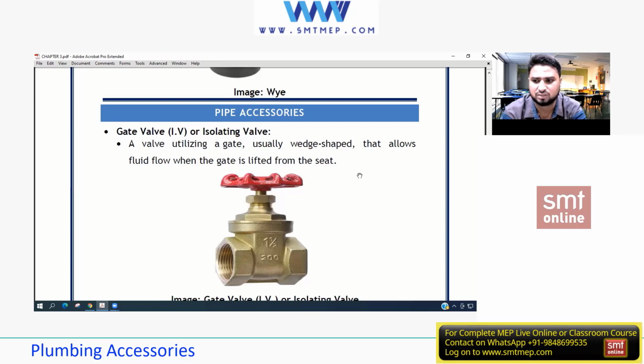Why? Because it's not recommended, for example, in a high-rise building with 10 bathrooms and 10 kitchen areas, that I totally disconnect the complete water supply just for one person who's suffering, right? So that would be open from the top, and here I'll be closing it. That means no water supply in this particular wet area, so that we can proceed with our work, isn't it? So different risers for this line.